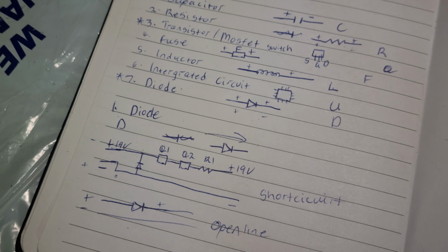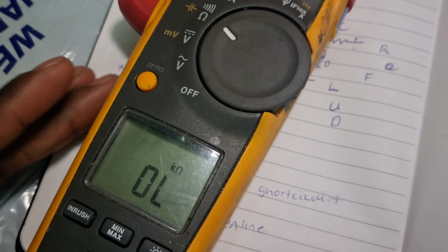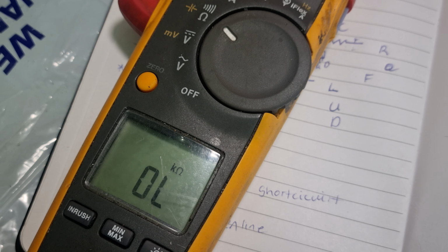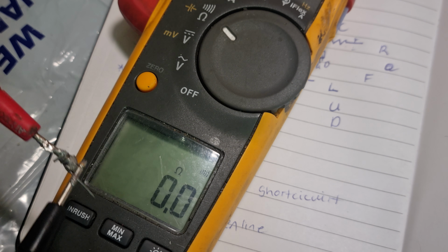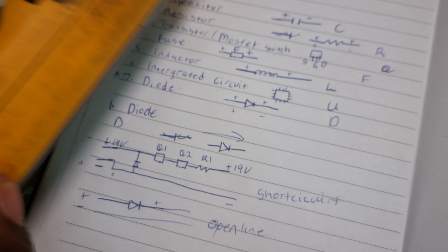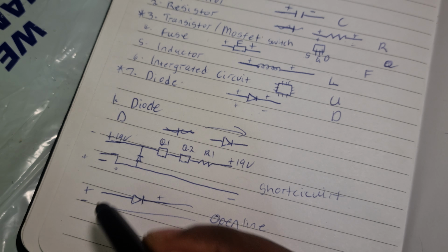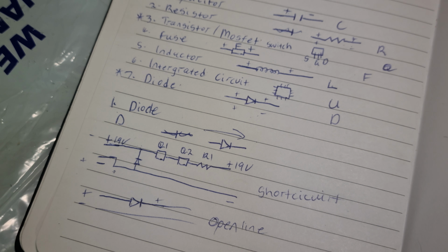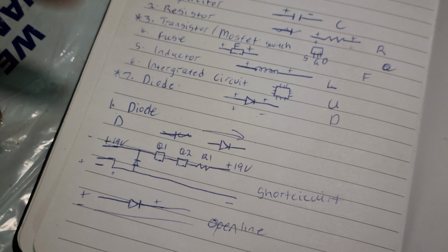That's why when you've got your multimeter powered on like this, it will say OL, open line, because it's not reading anything. When I do this, it says there's zero resistance, but when I do this, it says open line. So if this diode fails, there is no reading between negative and positive, so you just get an open line, in simpler terms. That's another application of a diode.